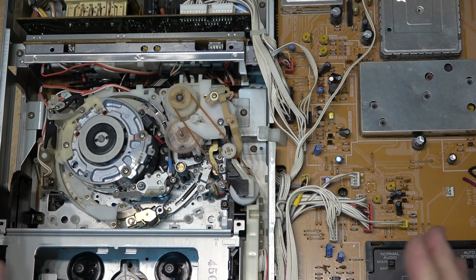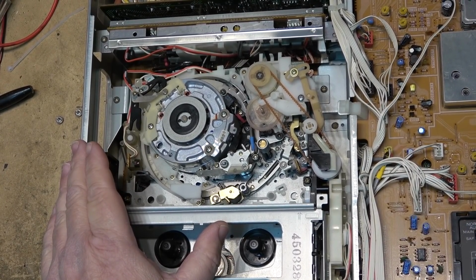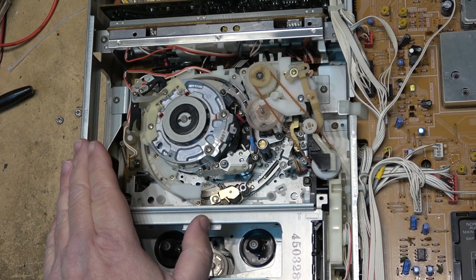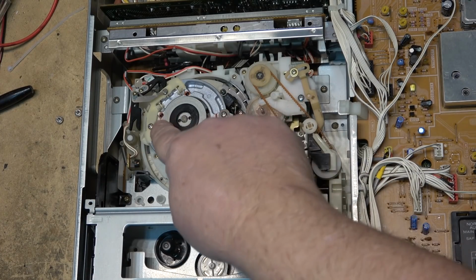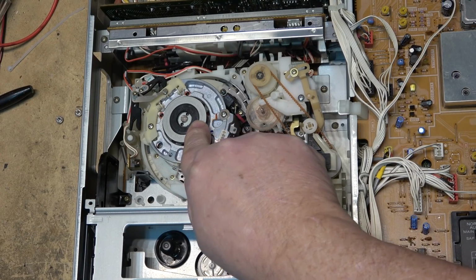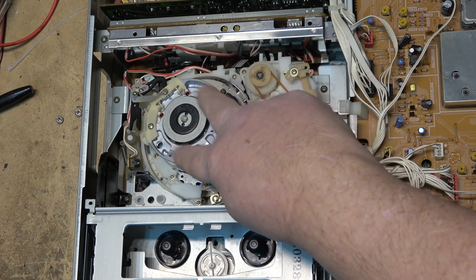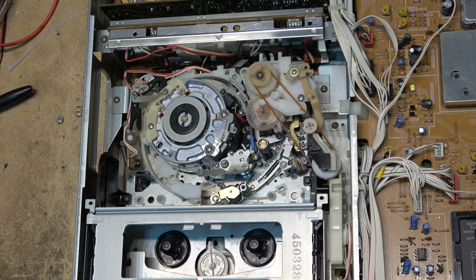The SLHF900 was their first quasi-editing deck. It had 4 heads, so 2 double azimuth heads, so it could do slow motion in forward and reverse and freeze frame, and it had editing capabilities, but it did not have flying erase heads. And I actually took one of my SLHF1000s, the head drum seized. The rotary transformer fell apart and it seized up. So I actually transplanted a 4-head drum from an SLHF900 and put it into an SLHF1000.